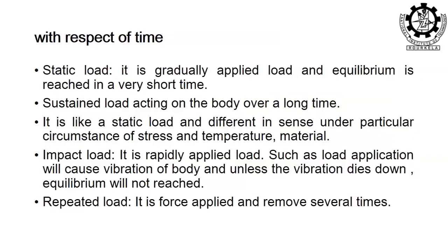It is like starting and different in sense under particular circumstances, like impact load. Impact load, most of us know what is impact, because every day on Indian roadways you will see all kinds of impacts. So, impact load is a rapidly applied load, such load applications will cause vibration, and unless the vibration dies down, equilibrium will not be reached. And repeated load, I need not discuss more because it is repetitive in nature itself.